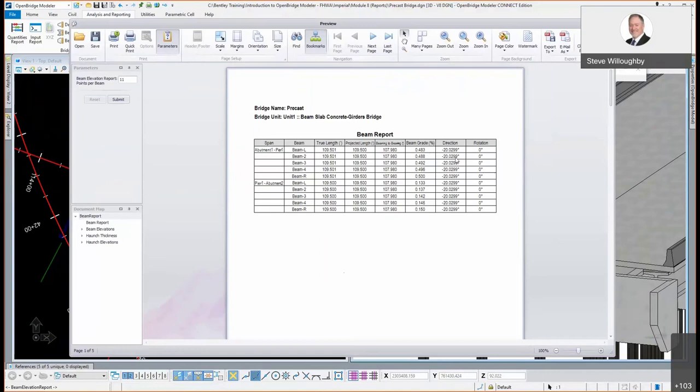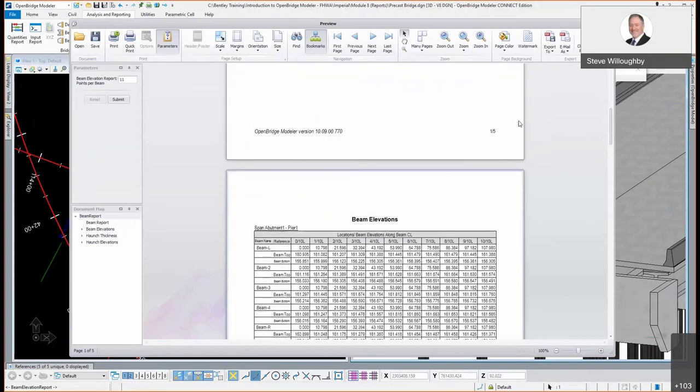Think kind of an angle, kind of a MicroStation angle, really, at this point, and then a rotation of the girders. And the rotation of 0 means they're true vertical, but there is an option when you place girders, and this is probably more common with box beams or U-beams or deck bulb tees or something like that, where they might be parallel to the bottom of the deck. The top flange is parallel to the top of the deck, so we can give you the rotation angle there if you use that option.